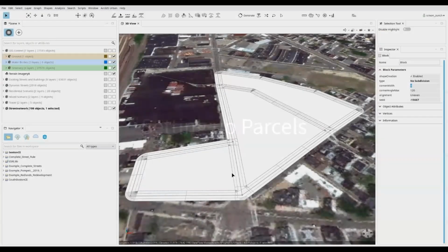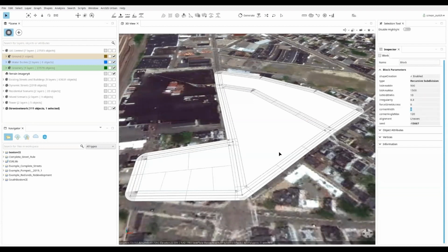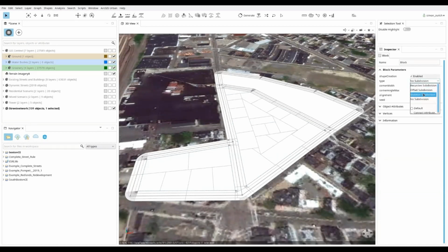Before we can continue with the buildings, though, we need to set up the parcels where the buildings sit upon. One approach is to refine the blocks which are automatically derived from the streets, so we can do a loop detection and find the blocks between the streets. In this example, we make use of the built-in block subdivision schemes. We have 3 hard-coded subdivision schemes: the recursive, the offset, and the skeleton subdivision. These loosely map to practices of urban planners.